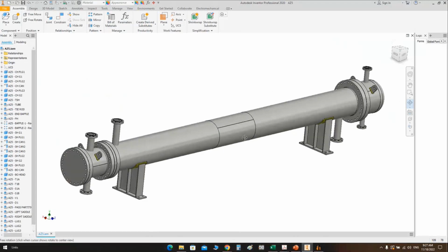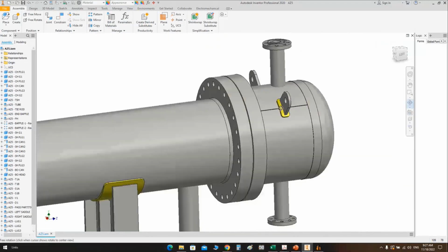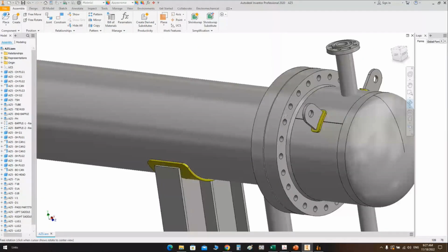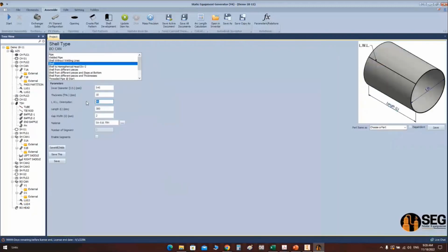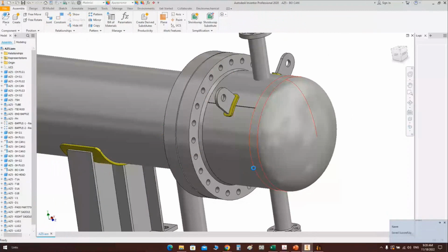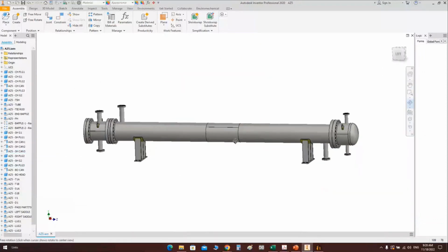Here, as you can figure, we have the same interference between the longitudinal building line on the bonnet and the lifting lug. As we discussed, you can go back to the bonnet CAN and change the longitudinal building line orientation and modify it. So the longitudinal building line orientation will be modified like that to be cleared from the welding line.